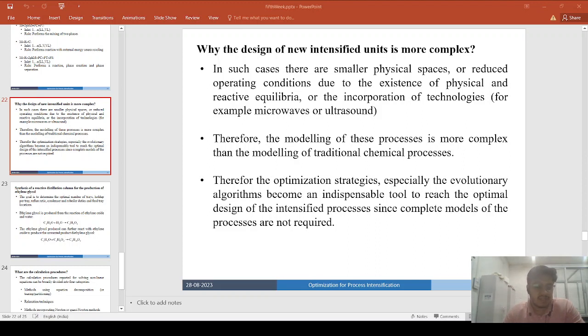And again, for the application in hybrid distillation with melt crystallization using thermally coupled distillation schemes, the optimization techniques can give you the design and optimization. The design and optimization can be carried out in this case, as a design tool, using a multi-objective genetic algorithm with restrictions coupled with the Aspen Plus process simulator. Now, for the application in biodiesel production in a countercurrent reactive extraction column, the Aspen Custom Modeler (ACM) can be employed, which includes the multi-objective optimization of the hybrid separation using evolutionary algorithms.